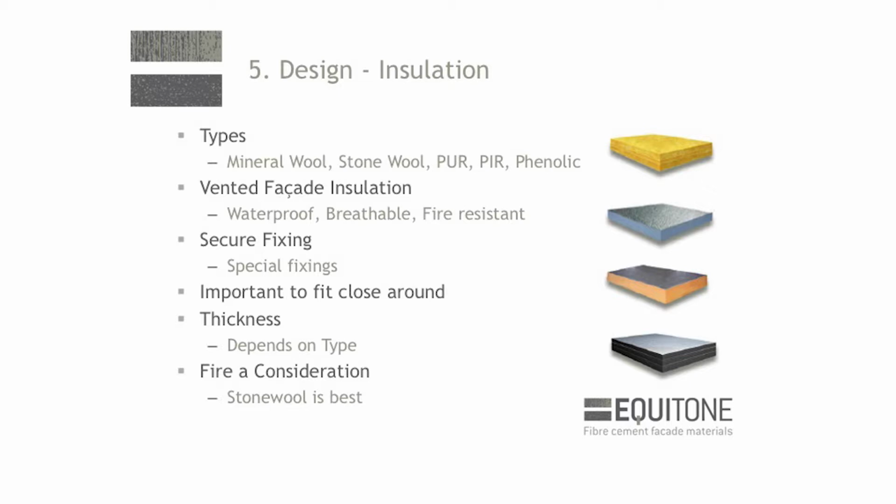They're generally breathable, they're waterproof, and they have some sort of fire resistance, except the EPS. Compared to what you normally use internally in partitions, they're a lot denser, and they're more of a batt, we call them. They're very rigid. And they normally would have a black coating on the outside, so you don't see them through the cavity.